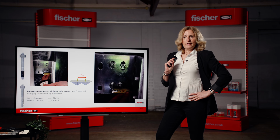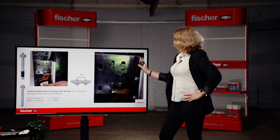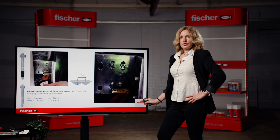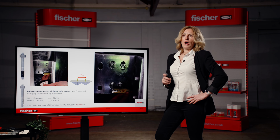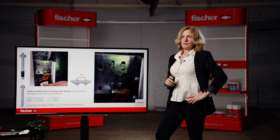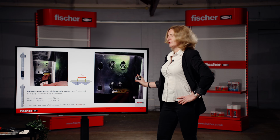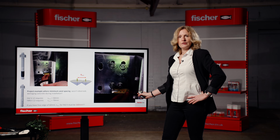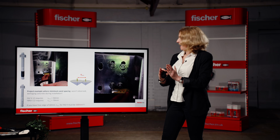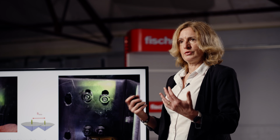Also, what is very, very, very important, in this case, they had also a free edge. If you are introducing a free edge on application, you need to check how you need to adjust the axial spacing. So for example, if you have edge distance of 60 millimeter from the anchor, then axial spacing has to be increased from 50 to 160 millimeters. To avoid the damage to the substrate.